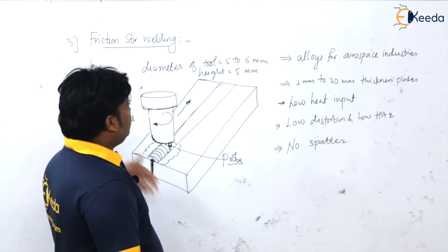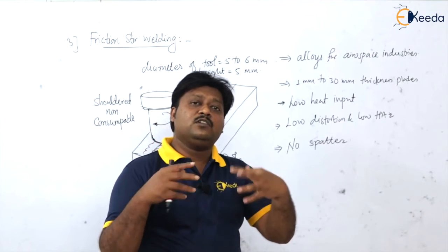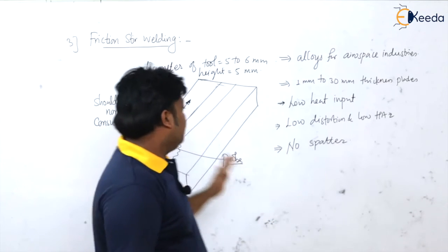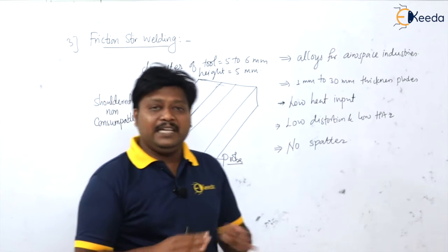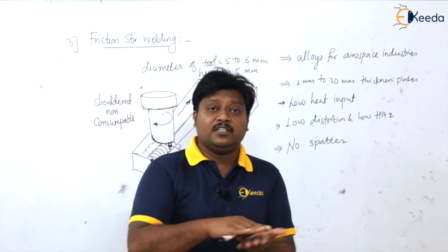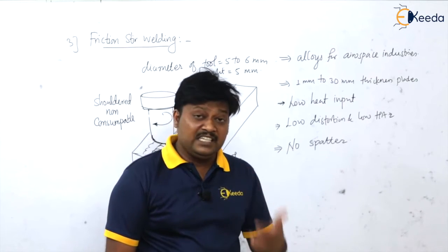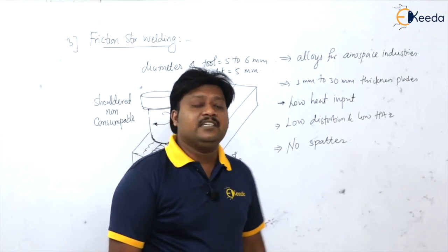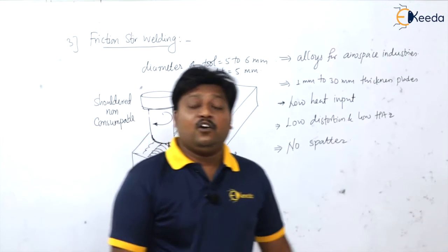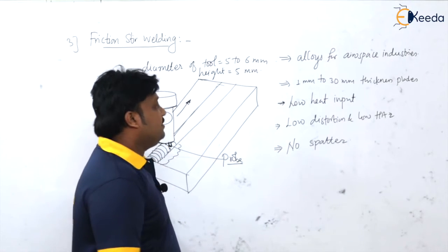So this is an extension of friction welding. Friction welding was used for symmetrical parts having rotational symmetry, but here we can join plates by using the third body, which causes the rubbing action and produces frictional heating. It raises the temperature of the joining surfaces, and the joint or welding can happen. So this is about friction stir welding.